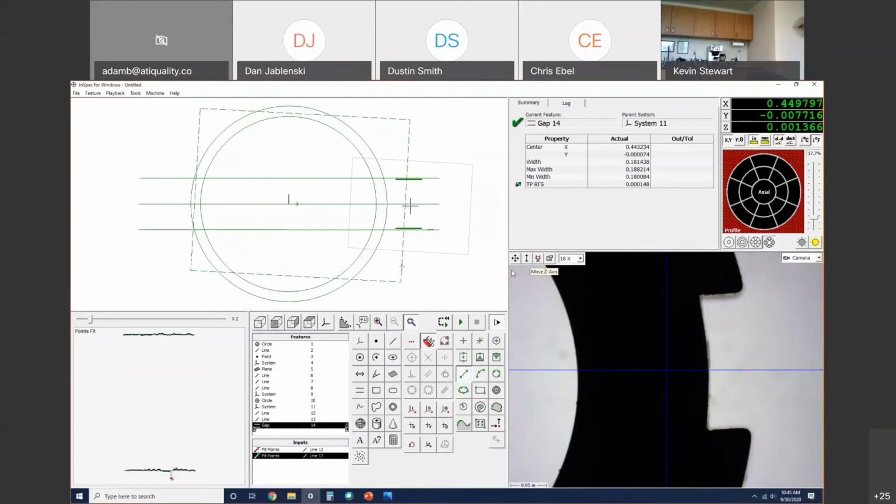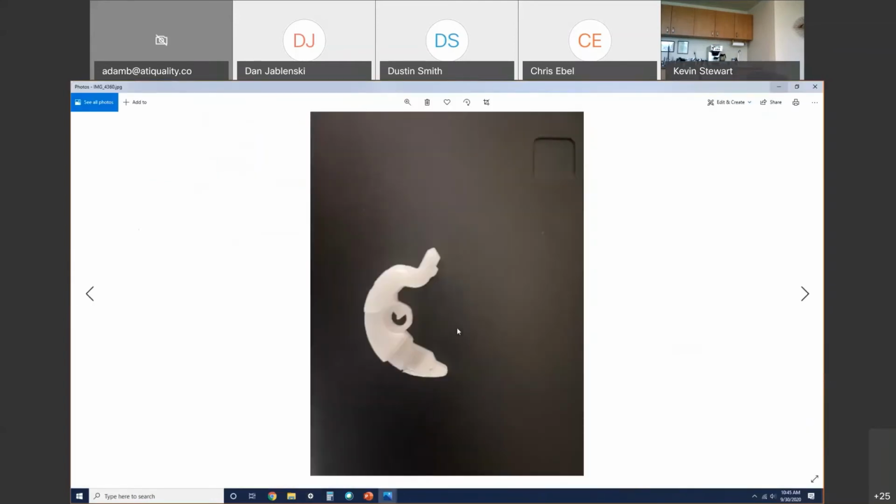So I have this last part here. It's a little blurry, I apologize, but the center diameter here is a datum. And the edge up here on the top of the part is another datum that we would skew to. Then I'm going to show you what this inside feature looks like. It's actually true positioning a gap down here. There are a lot of basic dimensions to this part, some that stack, some that are angles. So this part alone, just setting everything up, would probably be half this webinar.